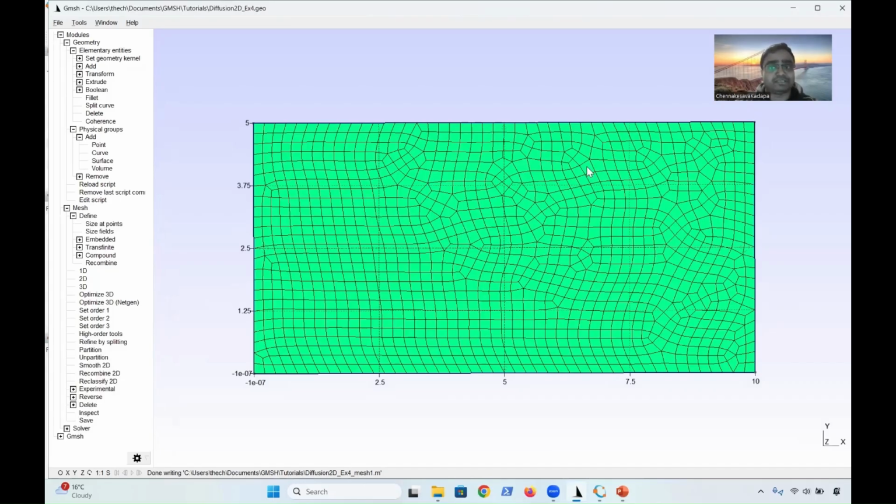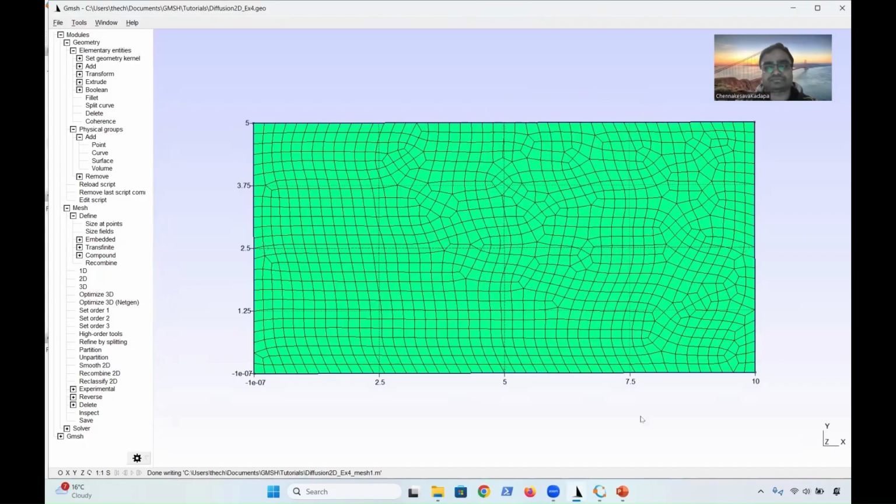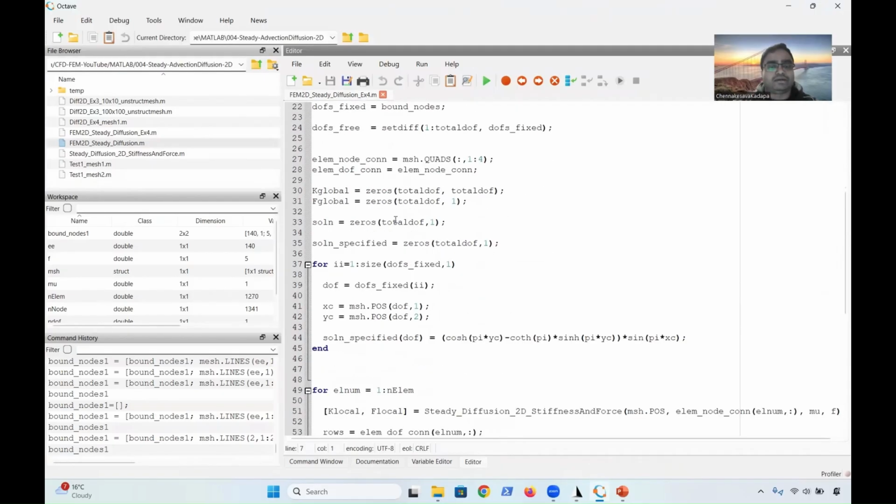Again, this is not a structured mesh. We have an unstructured mesh, but everywhere we have quadrilaterals. Let's check. Okay, there are no triangles. I import this. Now, for the boundary conditions, it is a constant value, so we really don't need the HC, YC values, but we can keep them. Everywhere on the left, bottom and right side boundaries, we have a specified temperature of 20 degrees.